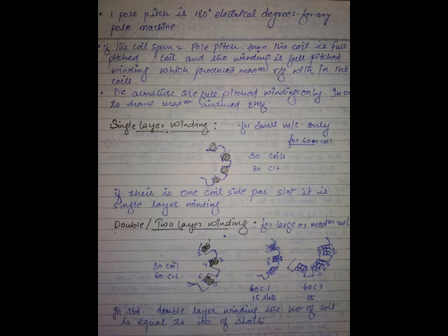So, come back now. These windings are connected in parallel in order to increase current rating and loading capability. I'll extend this after lap and wave again. I will connect these two waves because wave is advantageous over lap. There is a reason for that, then you will understand.